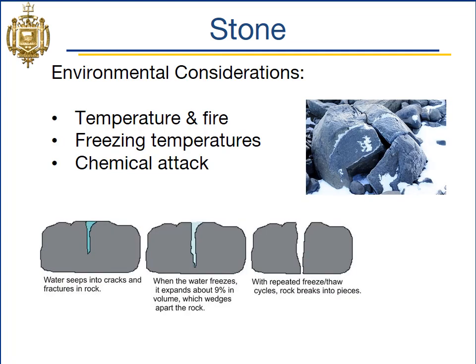durable. It's always important to consider the environment and how it affects your construction material, and stone is no exception, especially because it may have small cracks naturally already started. And so if water gets into a crack and then it freezes, the freezing strength of water actually exceeds the compressive strength of many rocks, and so it will cause it to crack. So that must be taken into account when choosing it as a construction material.